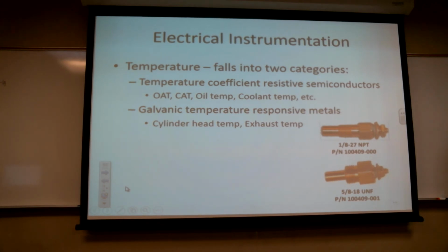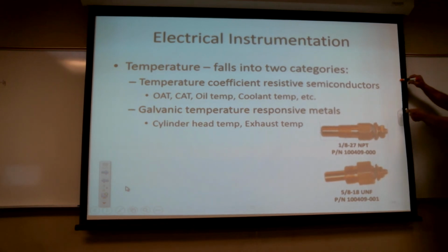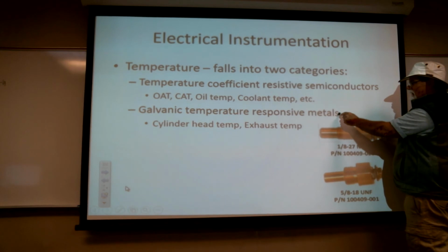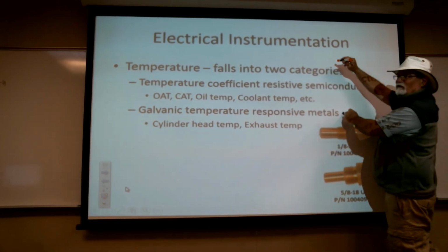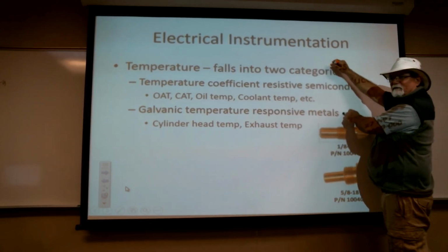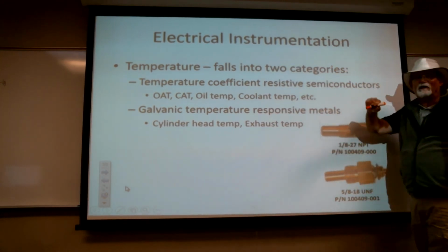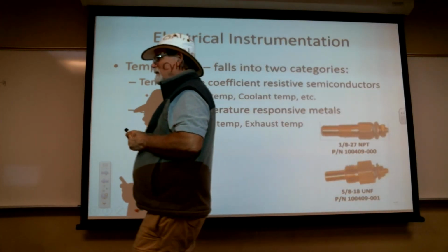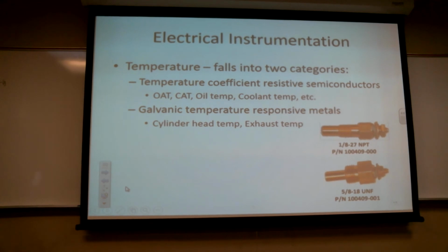Well, pretty soon, guess what? There I am with my voltmeter, measuring voltage drop. Get a little bit of a voltage drop from here to there, but not enough. But then I go from this housing to the engine, and I get another voltage drop. And then maybe from the engine to the airplane, I get another voltage drop. Shouldn't have any voltage drop on the ground side, should I? No. But voltage drop is my friend to help me figure out what the problem was. I've seen that a lot of times, surprisingly. I've even seen brand new auto manufacturers do that stupid one.